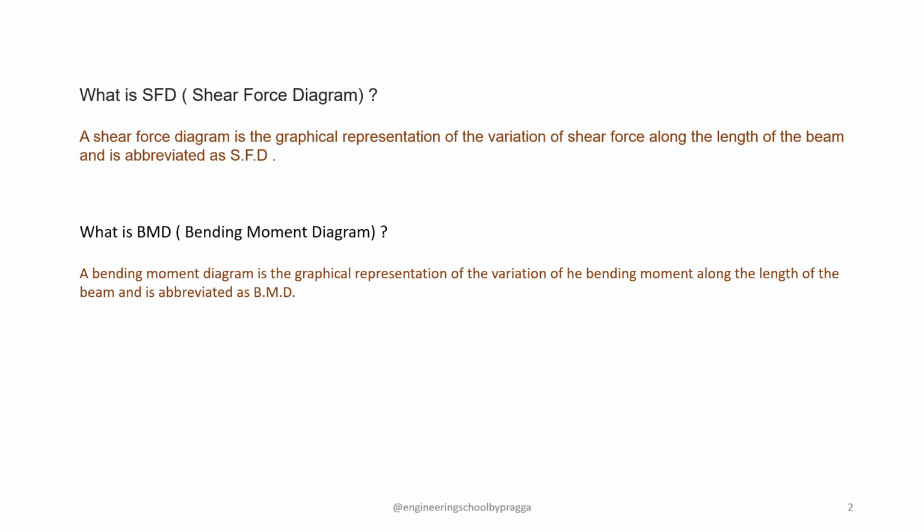What is SFD? SFD means shear force diagram. A shear force diagram is the graphical representation of the variation of shear force along the length of the beam and is abbreviated as SFD. And what is BMD? A bending moment diagram is a graphical representation of the variation of the bending moment along the length of the beam, and it is abbreviated as BMD.